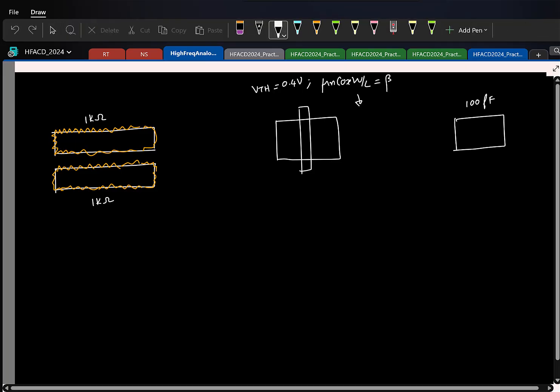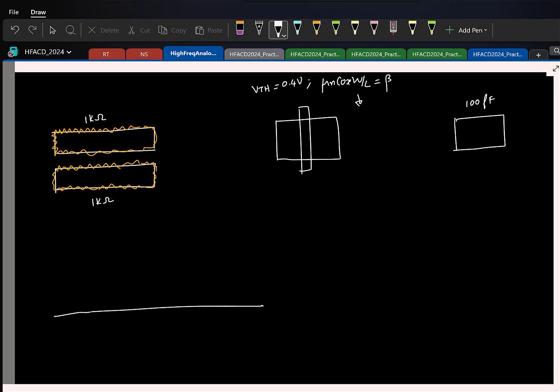So let us say in the x-axis I have all possible values for the resistors, and in the y-axis I plot the number of resistors having that particular value. How do you think this distribution will look? Gaussian distribution, again central limit theorem. We have a lot of independent, identically distributed random things adding up. Here also, multiple processes are resulting in this randomness. You'll have a Gaussian distribution like this.